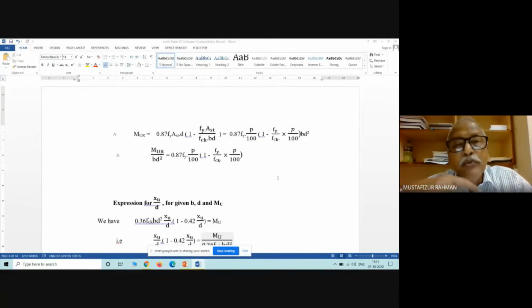So once we know the grade of concrete, fck is known to us. Similarly, we will utilize the steel, whether Fe250, Fe415, Fe500. In the normal case, Fe250 is nowadays not at all utilized. It is mild steel, stress is less.